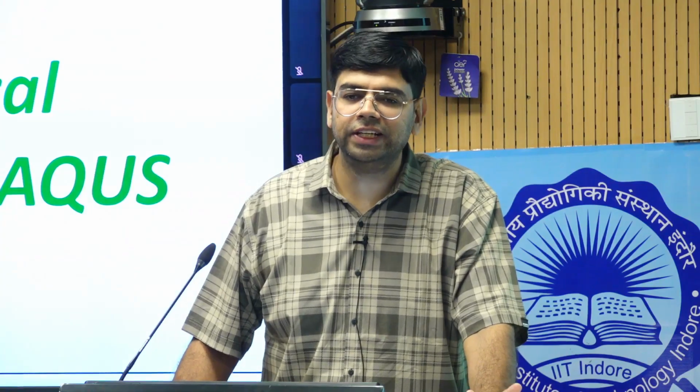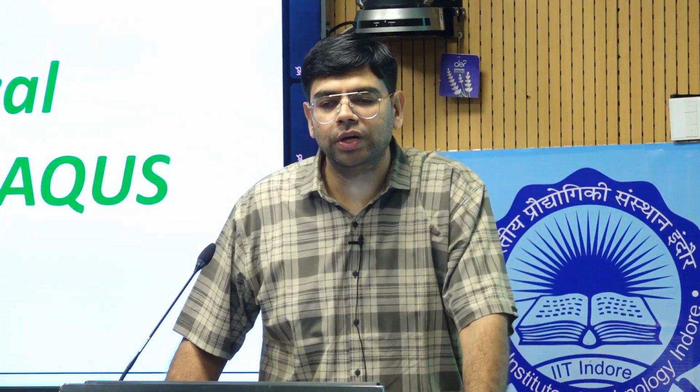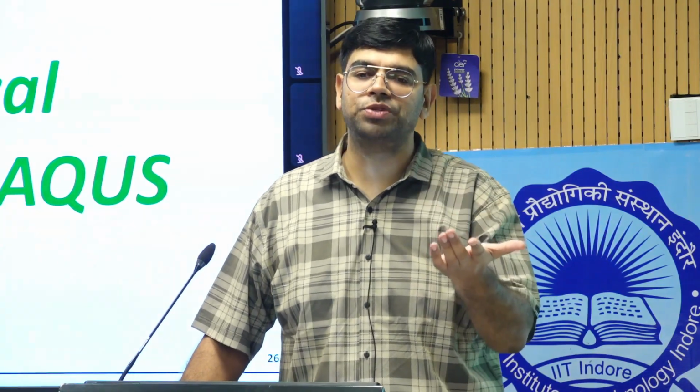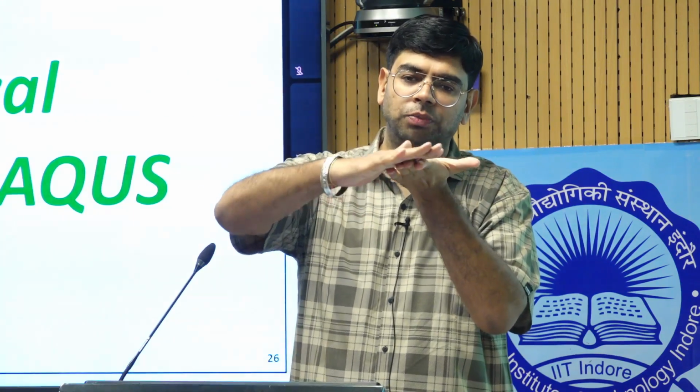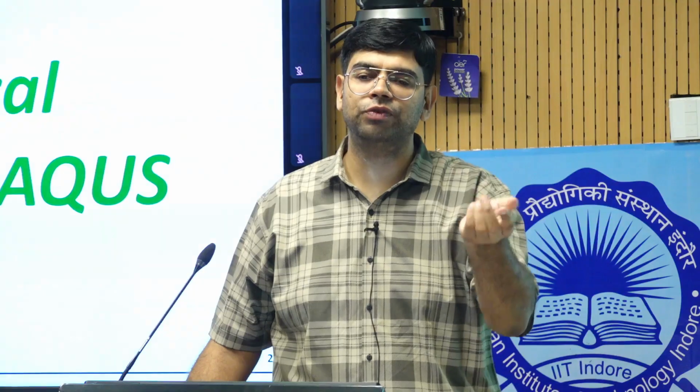In our case, the components are stiffener, frame, and membrane. In Abaqus, there is a tie option. For example, when combining the membrane with the frame, you apply a tie between the top surface of the frame and the bottom surface of the membrane, and they are going to club together.